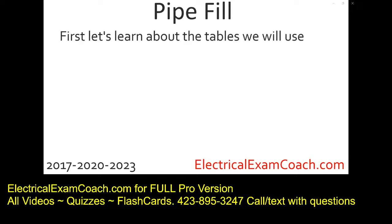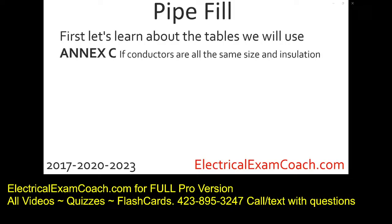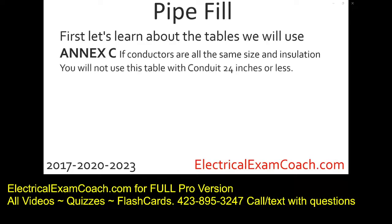Let's go ahead and learn about the table that we'll use if they are all of the same size. We're going to use Annex C. And if you've tabbed your code book, you have an Annex C tab. And if you haven't tabbed it, you can just follow along. If the conductors are all of the same size and insulation type, we get to use like a cheat sheet in Annex C. It's one of my favorite tables in the code book. You will not use this table if the conduit is 24 inches or less. Now, the code book uses the term nipples, but I want you to imagine in your mind, anytime the conduit is 24 inches or less, you're not going to use Annex C.